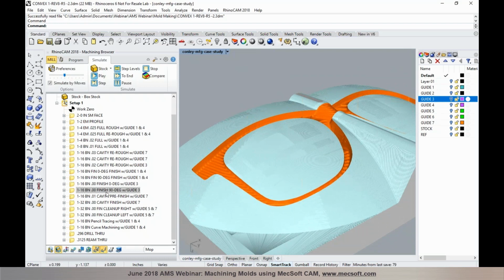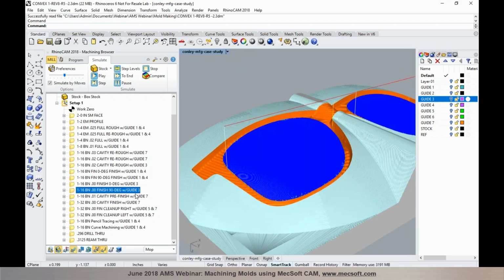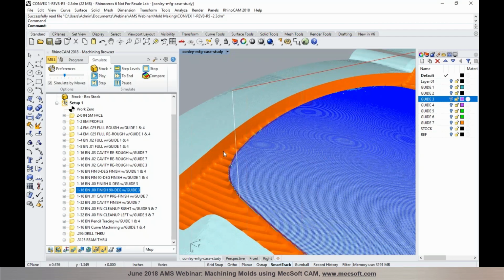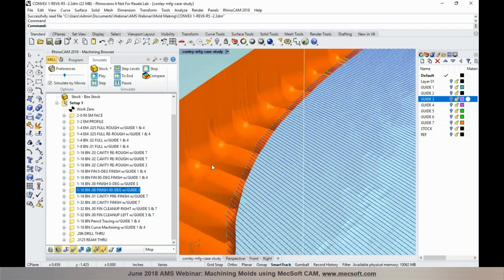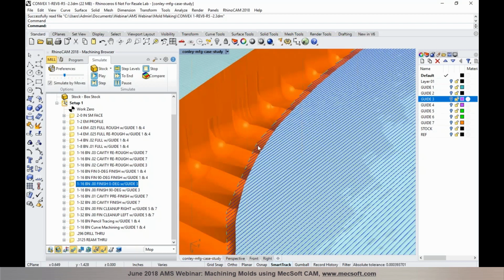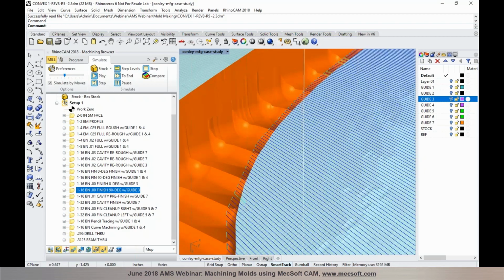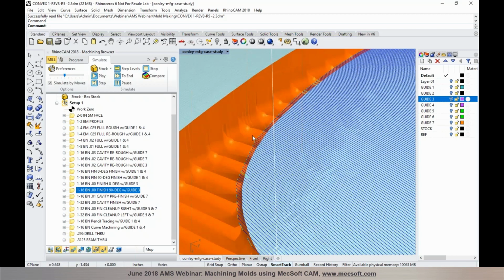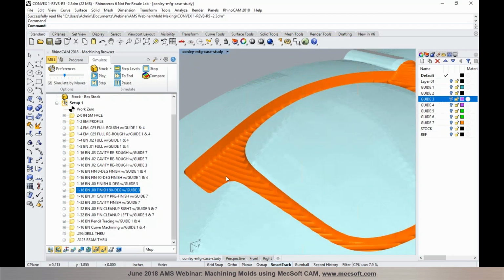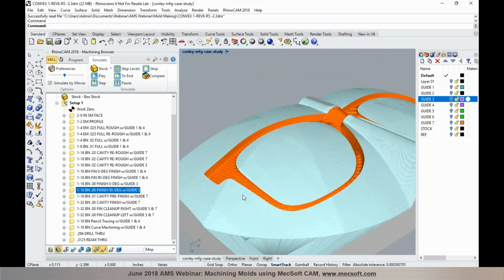So we also added another finishing operation in here by changing the direction of cut. In this particular step, we are cutting across. We're changing the angle of cut to 90 degrees. So whatever scallops you may have noticed being left from the previous step, which was set to parallel to X, or 0, are now cleaned up by changing your angle of cut in parallel finishing. So you're repeating the same operation and changing your angle of cut to result in a very fine finish on these cavities.